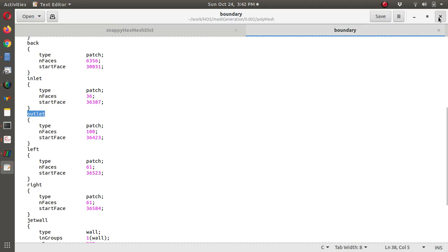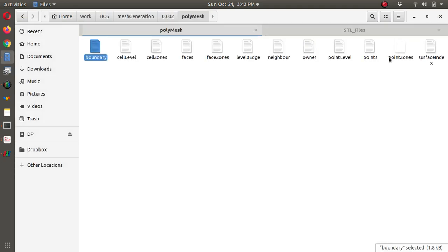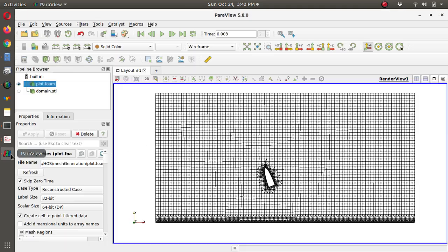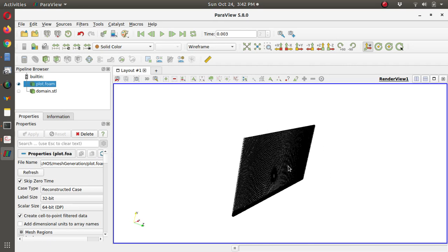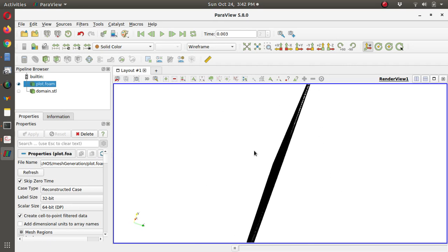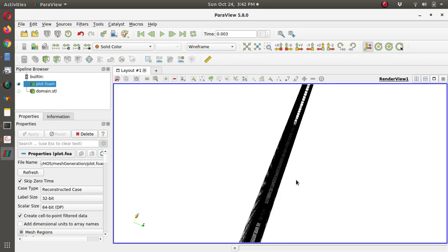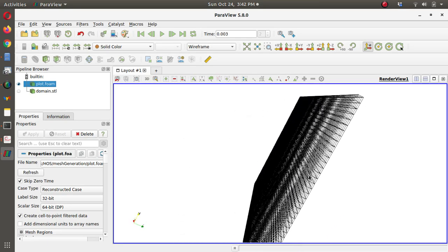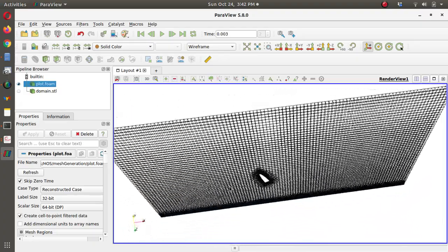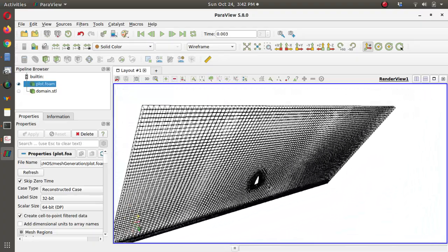Now after that, what we have done till now is just make a two-dimensional, very good mesh here. Then what we need is to extrude this mesh in our z direction, and we'll keep some more grid points so that it will be like an excellent three-dimensional mesh.